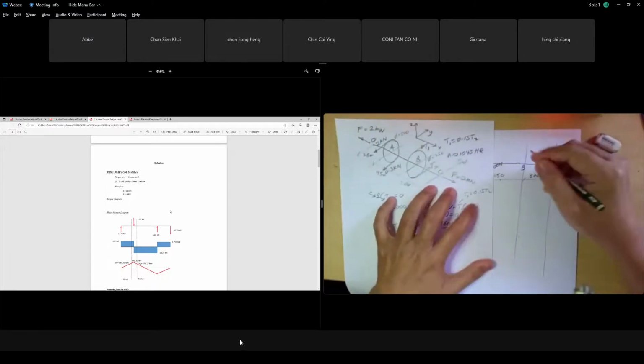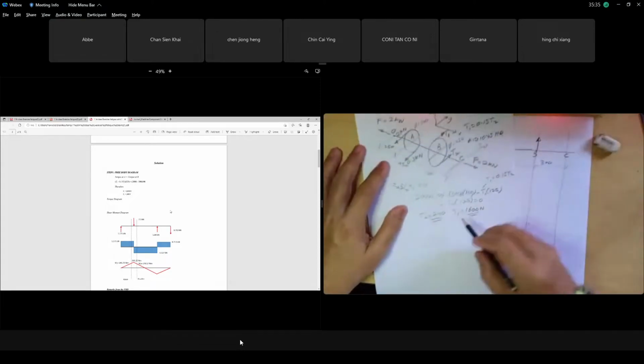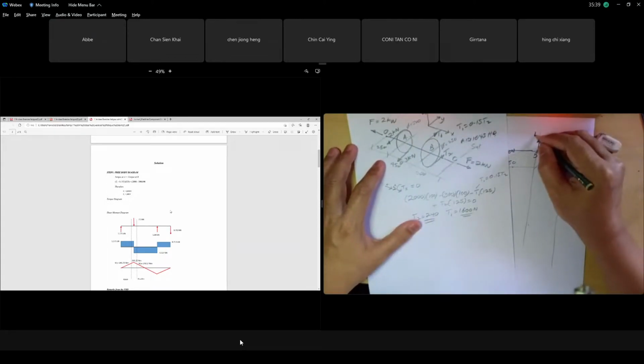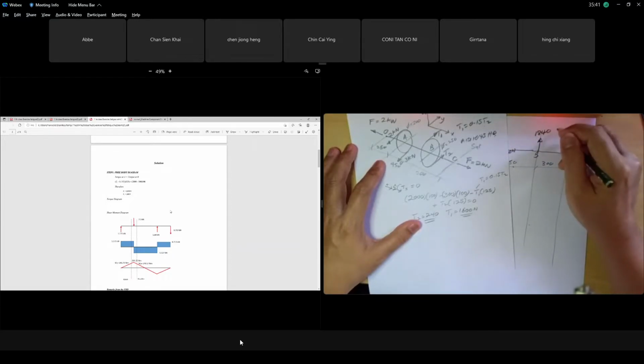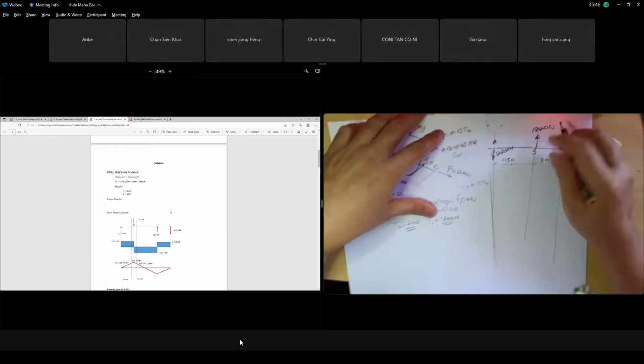Okay, at B we have all is upward lah. Total at B, T1 plus T2. At B we have force berapa tadi? Okay, T1 is 1,600, T2 is 240. So we have 1,840 Newton, or 1.84 kilonewton.